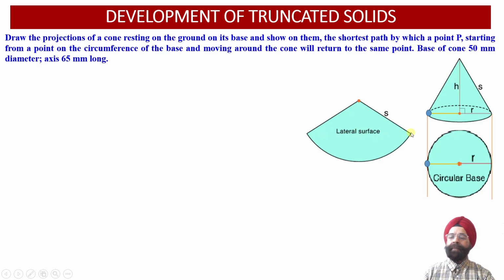And then whatever points of intersection will be obtained onto this cutting edge or a straight line or a string, which is going to join point A of the starting point of the developed surface and point A of the last point of the development of the lateral surface over here. So now the intersection of this string with all the generators, it can be 8 generators or it can be 12 generators over here.